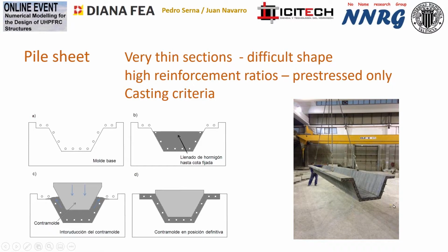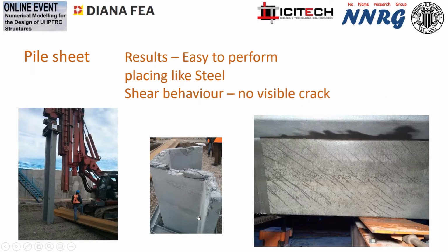What is this? This is a sheet pile. In what condition? This is clearly high pre-stress. You have a very high amount of pre-stressing strand. For pouring, clearly you have your formwork clear with the pre-stressed strand. You pour your concrete, with a counterpoint, in order to guarantee that the concrete goes up, and then this is easy to make. This is a good way to obtain a thin element. Usually we work with 5-6 centimeters in order to leave room for rebars.